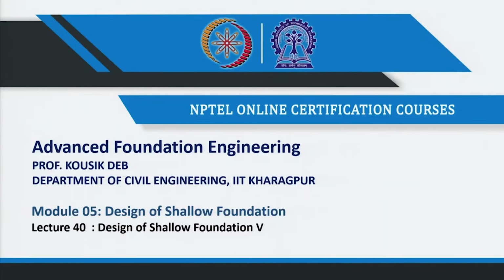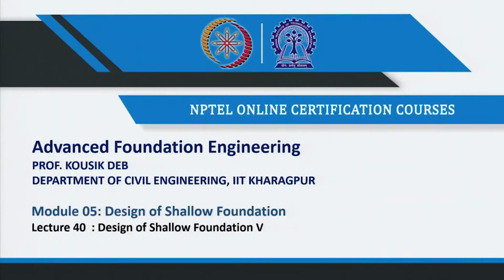So, in the last class I discussed how we can determine the bearing capacity of that raft foundation resting on the clayey soil, and it is observed that the factor of safety that we are getting for bearing capacity consideration is 7.1, which is greater than 2.5, and basically it is over safe. Now, in this class I will discuss the second part, that is the settlement calculation.